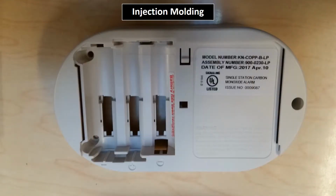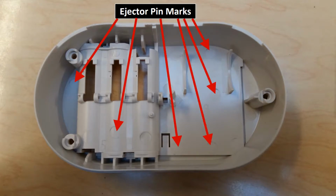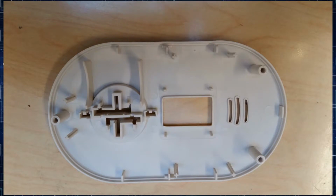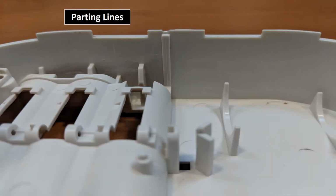Injection molding is good at producing parts with complex shapes and good dimensional accuracy. There are several indications of this method, the most evident being the ejector pin marks. Other indications of injection molding include the gate. The gate is a small opening in which the melted plastic flows into the mold. Another indication are the parting lines. The parting line is where two halves of the mold meet.